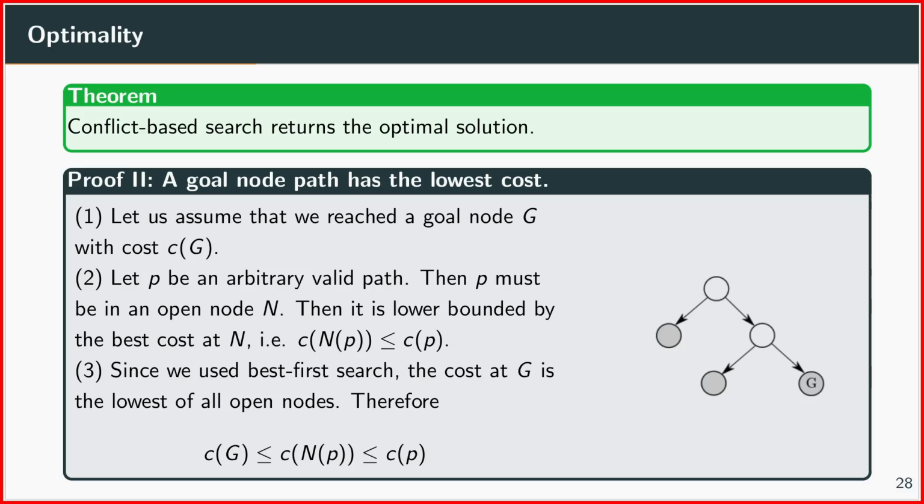Yeah, so basically what you do is that you just compute an A star shortest path search over the graph, and of course that could also entail that you wait at the start configuration. Okay, so that could also be another thing on the tree. Yeah. But I think in this case, I would say that this is actually the same cost as the path which I showed, if you just wait at the start configuration. So I think A star would just return you one of those paths.